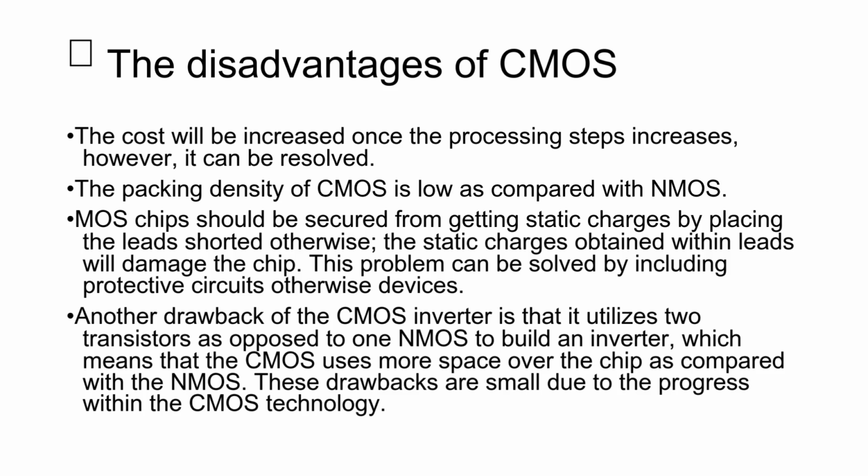Disadvantages of CMOS technology. While CMOS technology has many advantages, it also has some disadvantages that need to be considered. Some of the main disadvantages are the latch up issue. CMOS circuits can be susceptible to latch up, a condition where high current flows between power supply and ground. Then ESD, electrostatic discharge sensitivity. CMOS circuits can be sensitive to ESD, which can cause damage to transistors and other components. There will also be manufacturing complexity, yield issues, and design complexity. These are the disadvantages of CMOS technology.